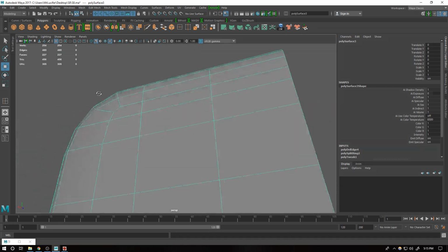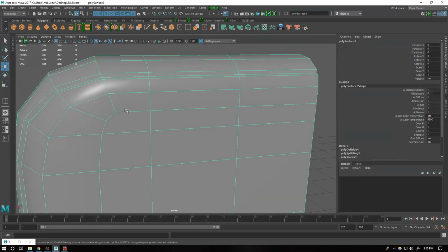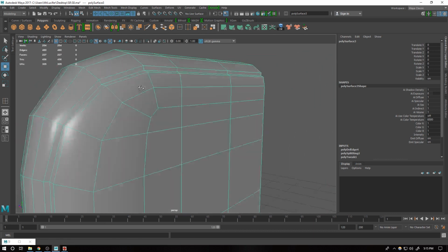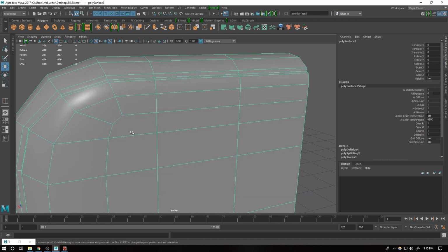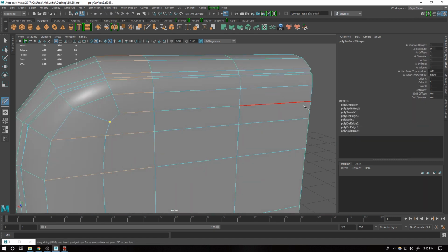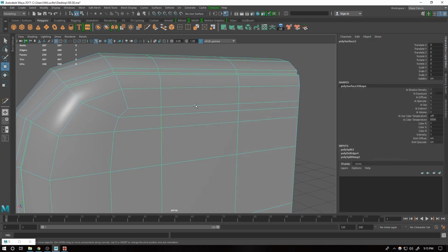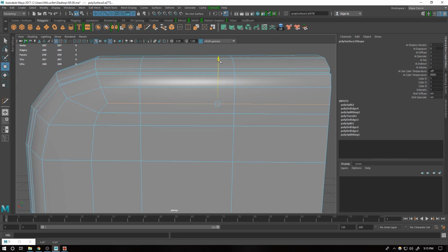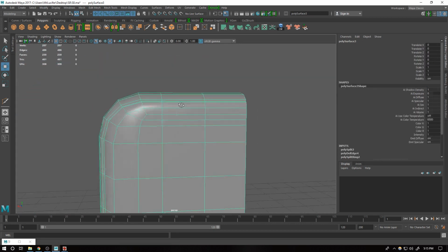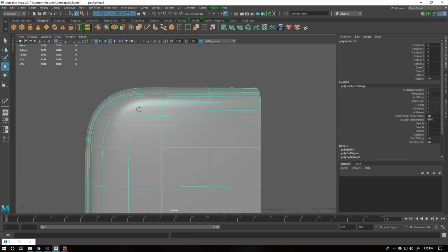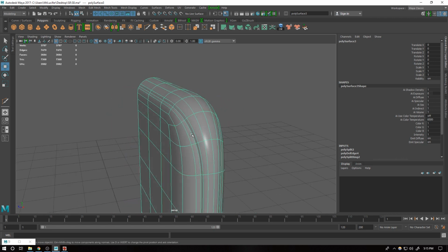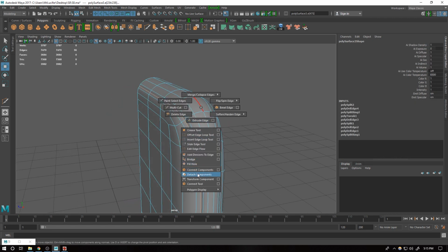It's better to have a pinch on the flat surface rather than on a curvature, right? So I rotate that loop towards this side so that I can move like this. That's how my loops go to a flat surface. This is a flat surface, it isn't going to affect anything. But if I have a triangle on a curved surface, that's really going to make my day.